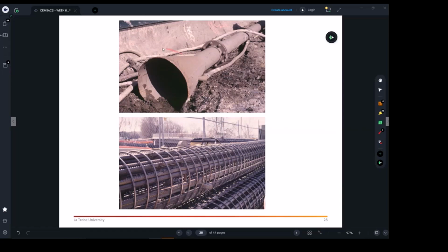This is the trimmer. That's the end which they use in the hole to help in cleaning the end of the pile at the very bottom, to scrape it and also to clean it, and to make sure you have achieved a flat end, especially if we're talking about 900 diameter piles.